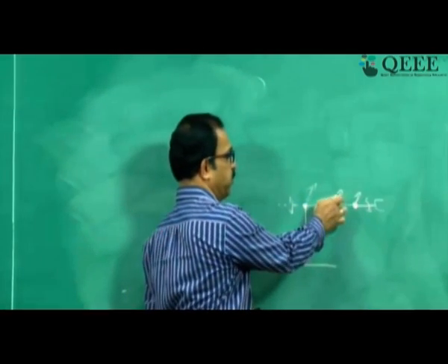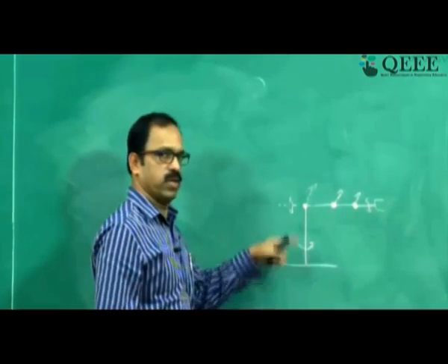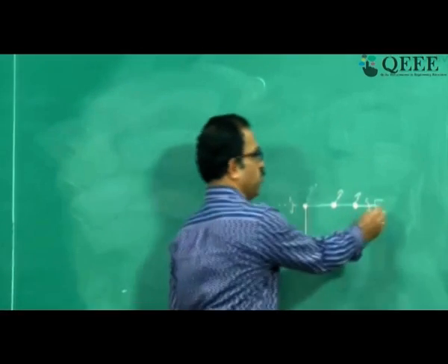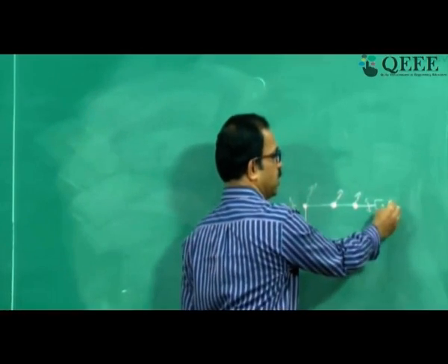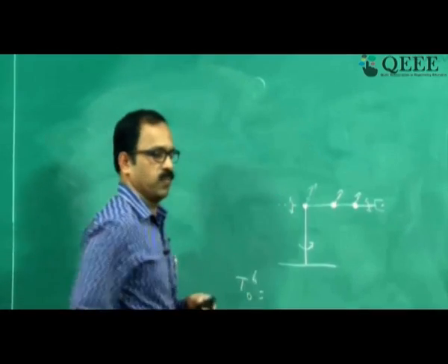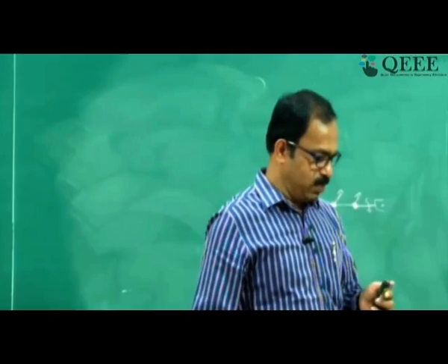It has 6 degrees of freedom, all the 6 necessary for manipulation, and for this manipulator, which has six joints, I want to get a relationship T6 to 0. So I want you to work along with me.